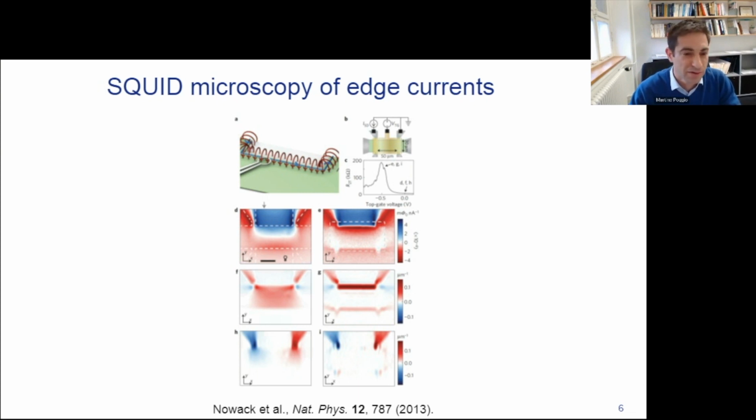This leads me to my main point here, which is that magnetic imaging techniques can be divided into two different categories: those that are sensitive to magnetization and those that are sensitive to stray magnetic field. Magnetization mapping techniques include the example of the spin polarized scanning tunneling spectroscopy that I showed in the beginning, the magneto-optical microscopy, and the Lorentz microscopy. These are direct measurements of magnetization, and they're very attractive for investigating magnetic domains and spin textures, but they have some restrictions into what kind of samples and conditions they can be applied to.